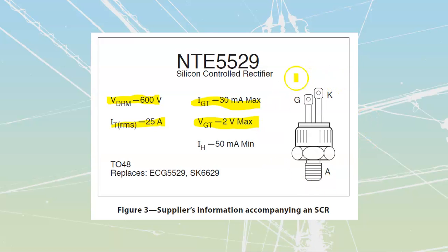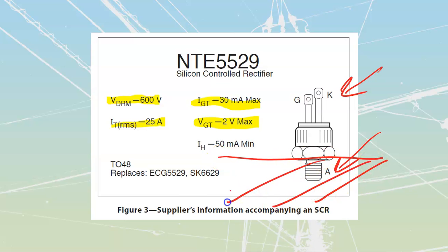Take a look at your actual connections over here. You're going to have your anode over here, your cathode over here, which means that if this is attached to any sort of heat sink, an industrial heat sink, that heat sink is actually going to be charged. It's going to be at a positive value of voltage for this thing to operate. Be very careful around industrial equipment. If you open something up and you see a heat sink, I know a lot of heat sinks are connected to ground, but you have to be very careful about which ones you touch. If it's isolated and inside of a cage or a component casing, there's a good chance that thing is actually live. Don't assume that these are all going to be dead.